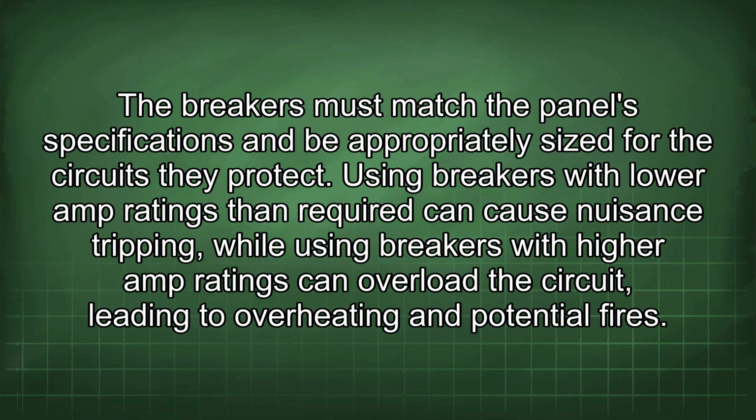The breakers must match the panel specifications and be appropriately sized for the circuits they protect. Using breakers with lower amp ratings than required can cause nuisance tripping, while using breakers with higher amp ratings can overload the circuit, leading to overheating and potential fires.